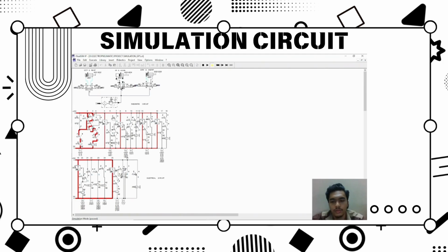Then relay contact -KF1 will close to make a latching in the circuit, and relay contact -KF1 will close and flow current through relay contacts -KF3, -KF5, -KF7 and -KF8, a normally closed contact, to activate solenoid coil -MB3. Then it activates the left switching position and allows flow from port 1 to port 4, and the piston rod of -MM2 will fully extend for the double acting cylinder.